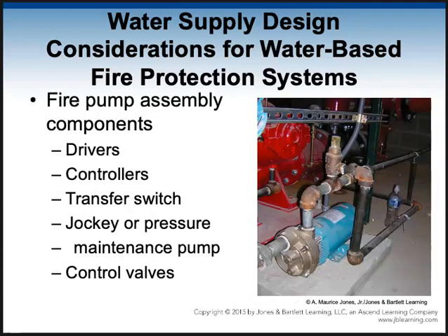Some of them will be jockey pumps. So a jockey pump is one that's just helping the pressure at a certain floor or just to boost it a little bit, whereas the big pumps at the bottom will be serving the predominance of the building. So these are going to require lots of drivers, controllers, switches to turn them on and off. They are very high maintenance, and that's why the facility managers have to be constantly checking them, periodically running them and testing them.